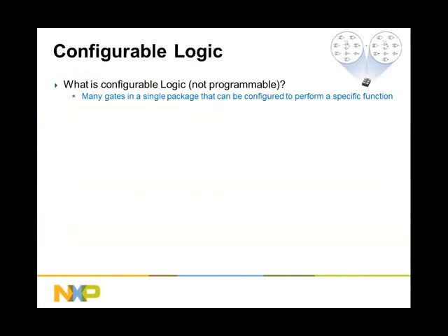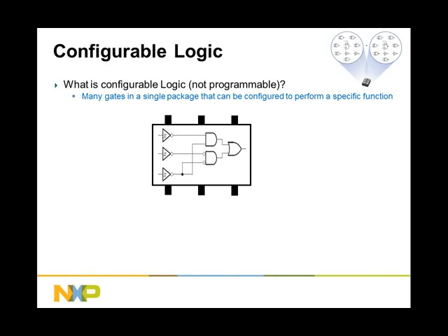So what is configurable logic? Configurable logic, first of all, is not programmable. It is configurable. It's where we put many gates into a single package that can be configured to perform a specific function. So here we have a block diagram of a typical configurable logic device.